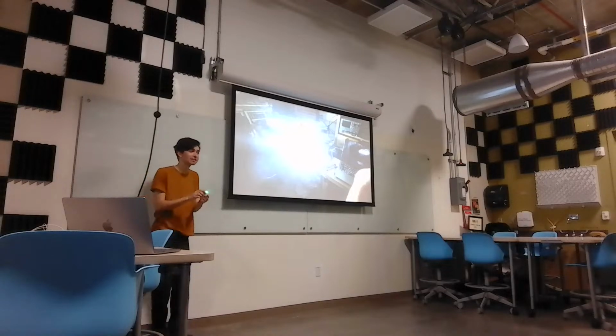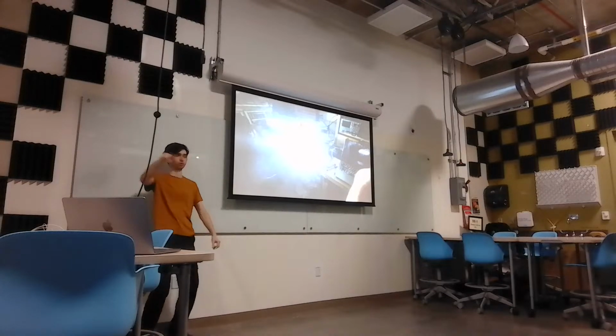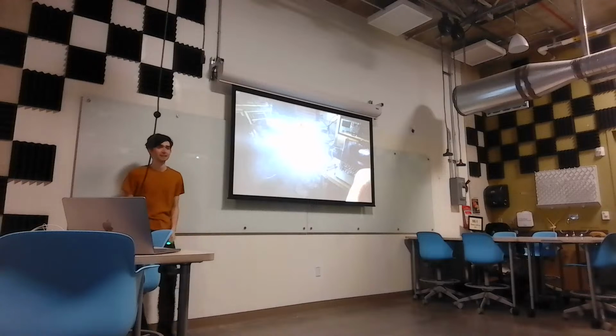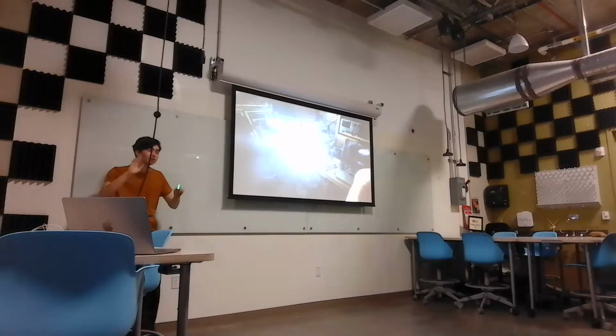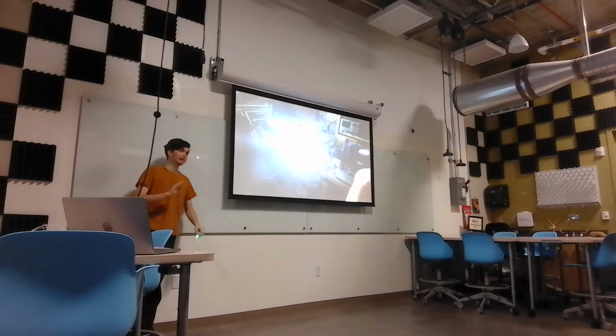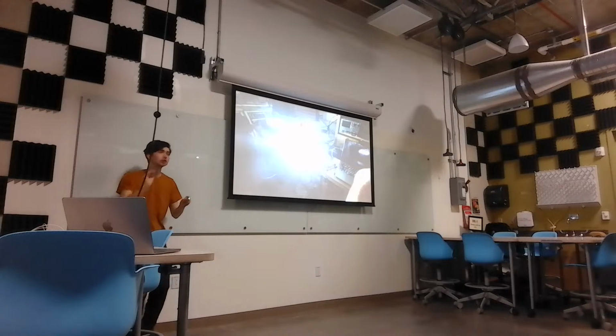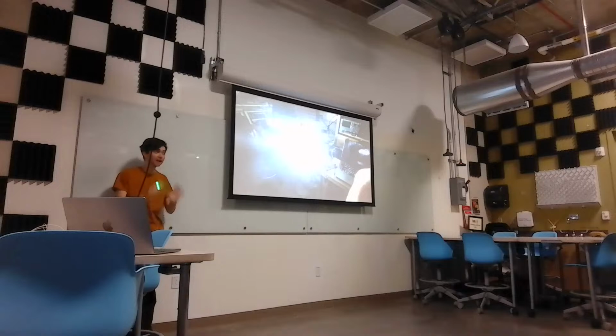But I don't know if you noticed, that waveform had a little lump in the front of it. My oscillation mitigation measures were not even close to over. Great. I added the absolutely necessary capacitance on the input, but now there's a lot of very sensitive work to make that waveform nice and straight, right? We're going to talk about that.